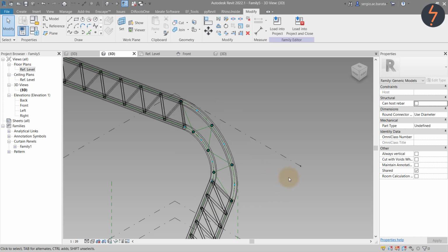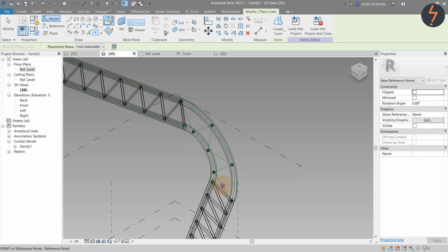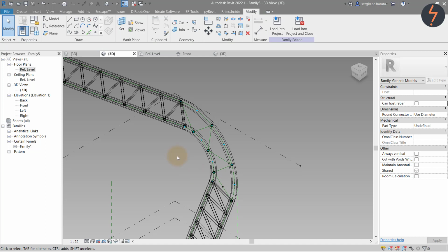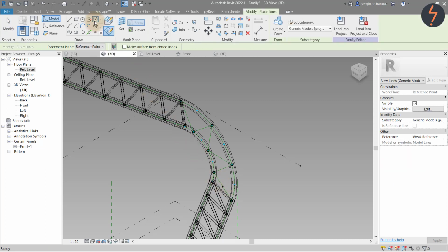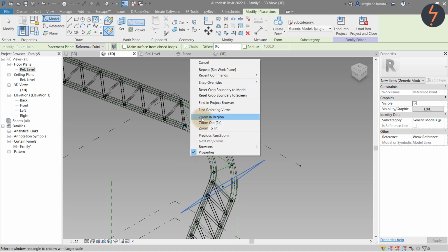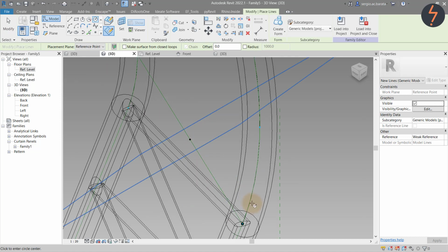On the Draw tools, pick Point and place a point on the bottom line of the zigzag reference. Then, you guessed it, set the work plane for that point. On this plane, make sure Draw on Plane is selected in the ribbon. Sketch a circle as shown, then select the profile and path and create the solid.